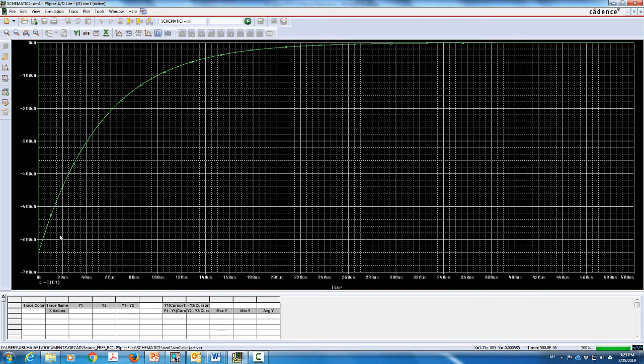You can see that the current through the capacitor was 0 initially, then it dropped to negative 600. And you can see that the current through the capacitor is not continuous. The voltage is, but the current is not. So it dropped to negative 600 micro, and then it started to basically increase exponentially until it fully discharges through the load.